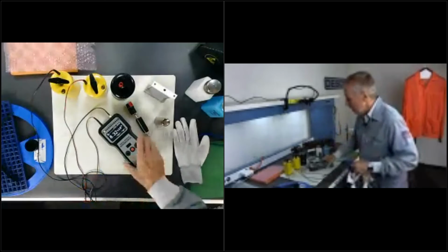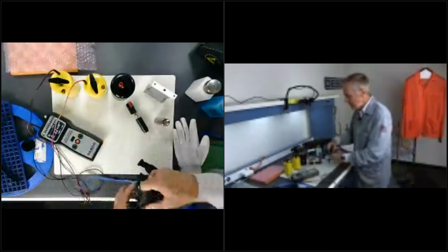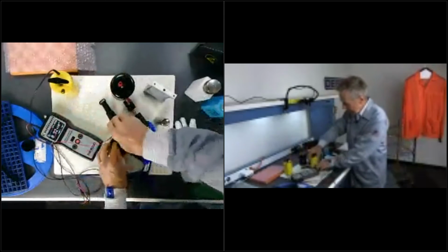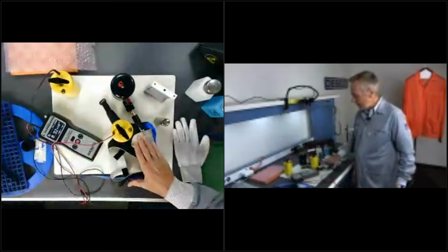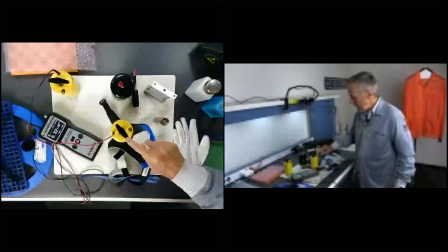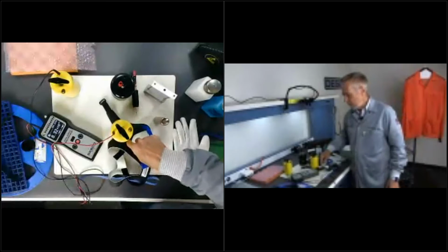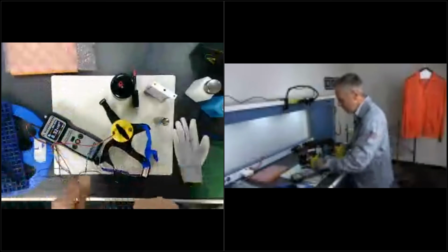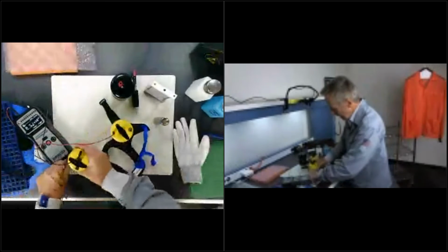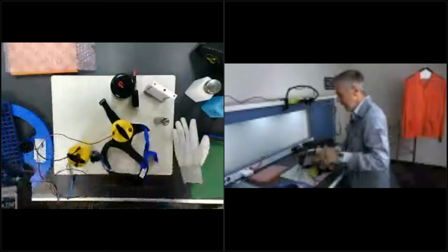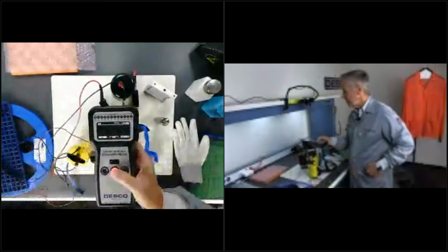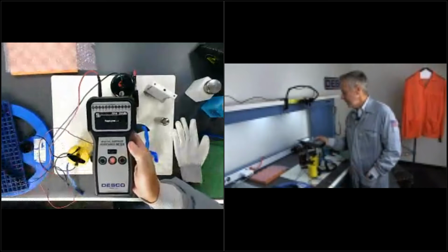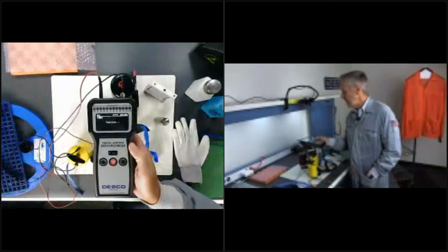the foot grounder. So one of the things you can use your resistance tester for is, this is a full coverage foot grounder, I can put one of my 5-pound weights on the conductive material, and then I can put a 5-pound weight on the ground tab here and take my measurement and see if that's in spec. So again, we're waiting our required time.